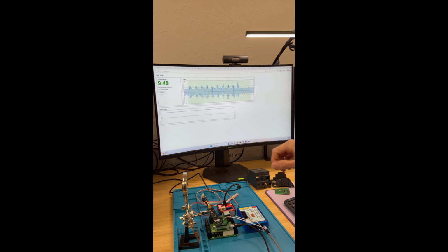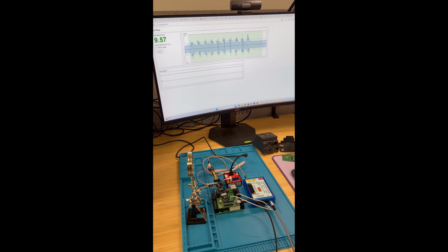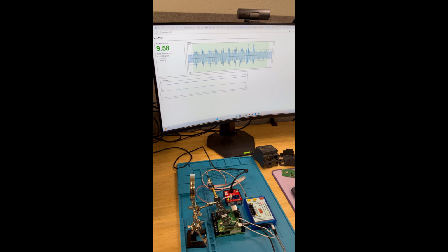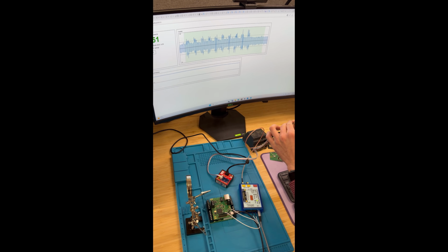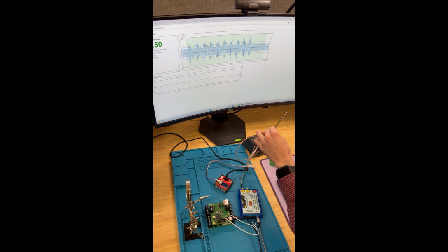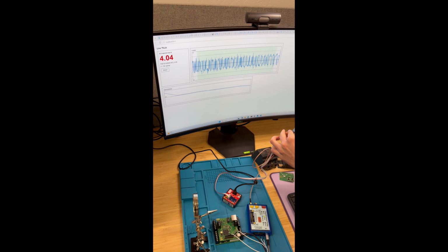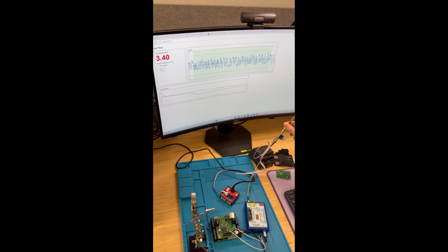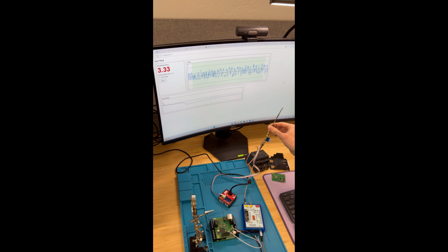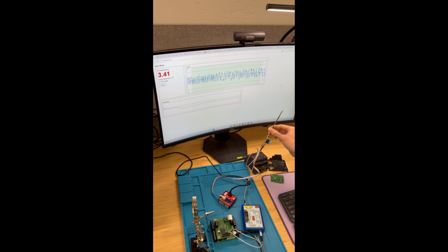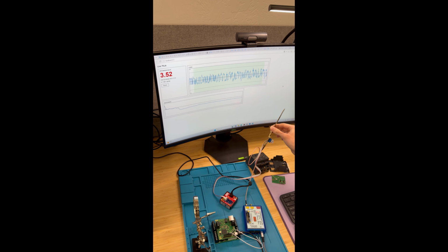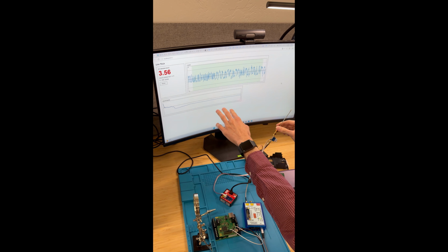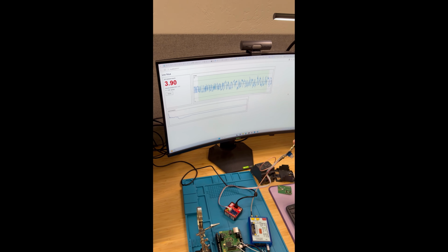And so you can see here, we're localized over that part of the chip, over our hotspot, and we have meaningful leakage appearing. And here's a look at what happens when we pull it out. We reset our trace accumulation, and we start just accumulating noise. Since there's no leakage anywhere here, it's just pure noise, we're not going to see anything crossing the T-curve threshold, and our line here of max T is just flat, pretty much.